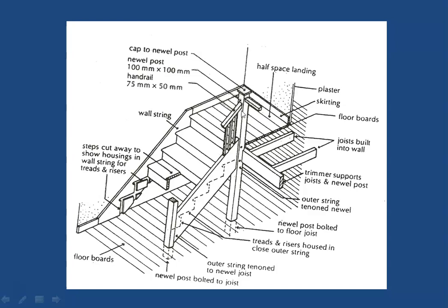In this case, the newel post is going right up to the bottom to support or to transfer the load from the stringer. You can see the second newel post at the bottom, into which the stringer is fixed. The joint between these two will be a double tenon mortise joint. You can see these two pin holes here in which the wooden pins are inserted, and so on. So you can see more details of the stair in this sketch.